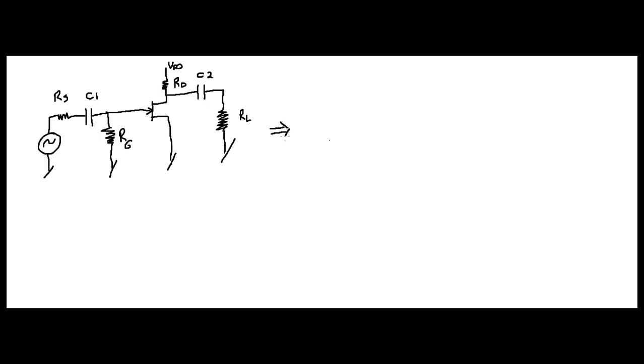So remember, at high frequencies, these capacitors basically don't have any reactance. So there's no impedance to current flow. So those basically can go away and be replaced with a wire. So let's draw this again, shall we? So we're going to keep your source. Why don't you all do this along with me, because it will help in your understanding. The more you draw it, the more intuitive it's going to be, right?